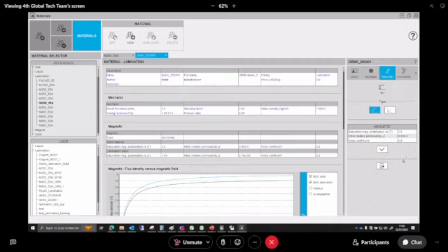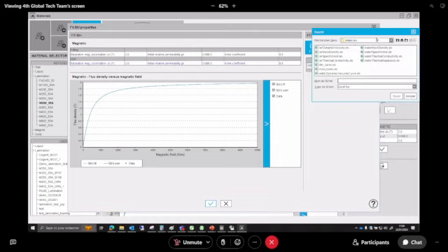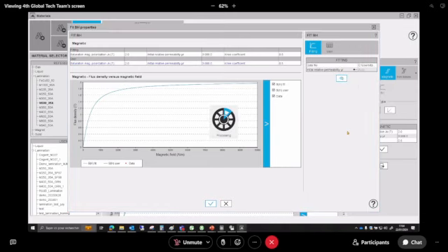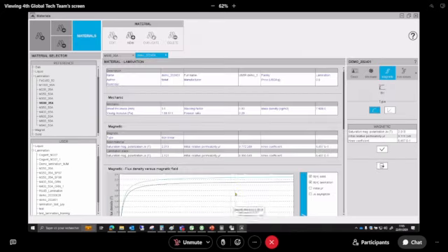If I have the coefficients, it's good, or I can have the BH curve directly, that I can select the file of the BH curve I have, and then I can import it, and then make a fit of this BH curve to have an analytical model. You can modify it a little bit if you are not happy with the fit. Then, okay.